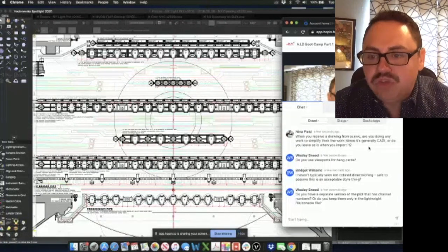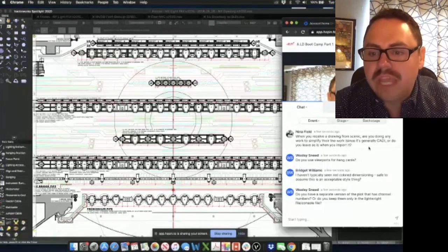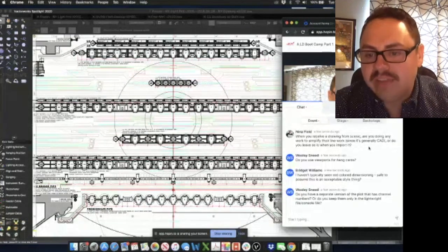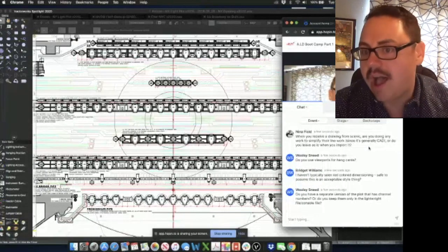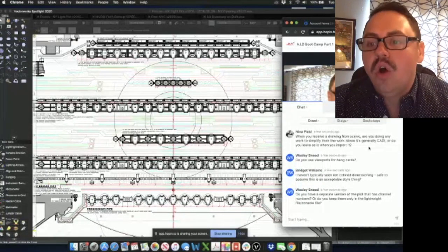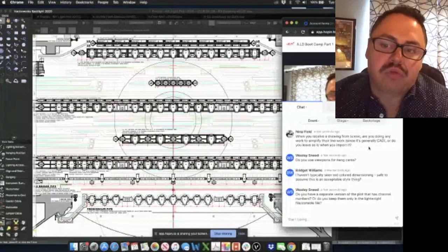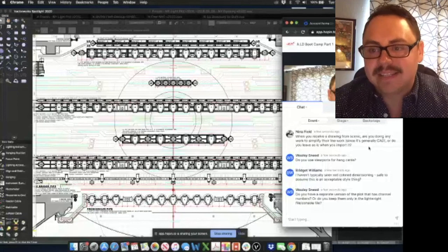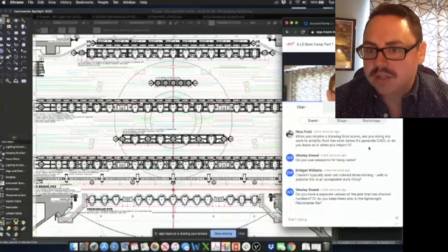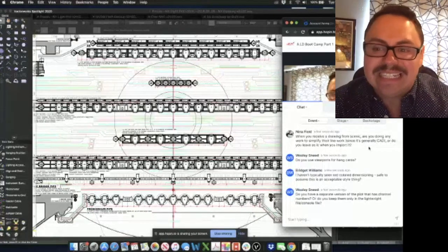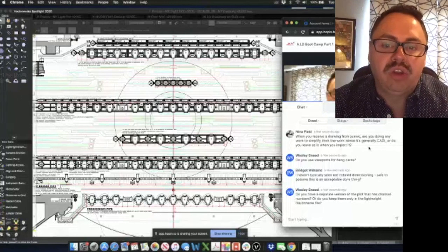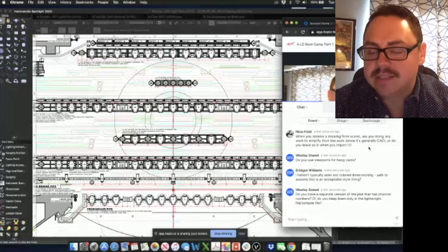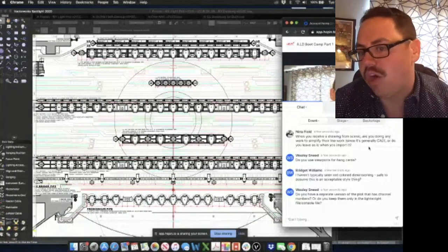Nina asks, when you receive a drawing from Scenic, are you doing any work to simplify their line work since it is generally CAD, or do you leave it as is when you import it? I do a ton of work. I can spend usually 2 or 3 days cleaning up a Scenic drawing. They're going to use a lot of classes that we don't want. I go through and I will delete stuff because some of them will include construction drawings and notes and everything else. And the point of my drawing is I don't want that on there.